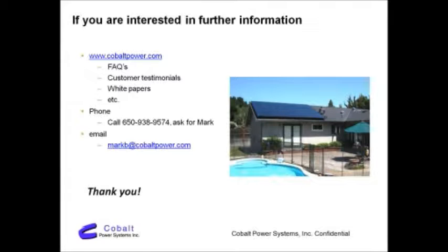If you're below 100, you're probably going to be doing it for environmental reasons rather than for financial reasons. Because in PG&E territory, you have a tiered rate schedule, and you're probably mostly at baseline or tier 2, where electricity is sort of inexpensive. And so you're replacing somewhat inexpensive electricity, and it's going to take you longer to break even. So where you saw that 4 to 5 year break even, if you had a $100 a month bill, it might be more like 7, 8, 9 years even, depending on which direction your array faces.